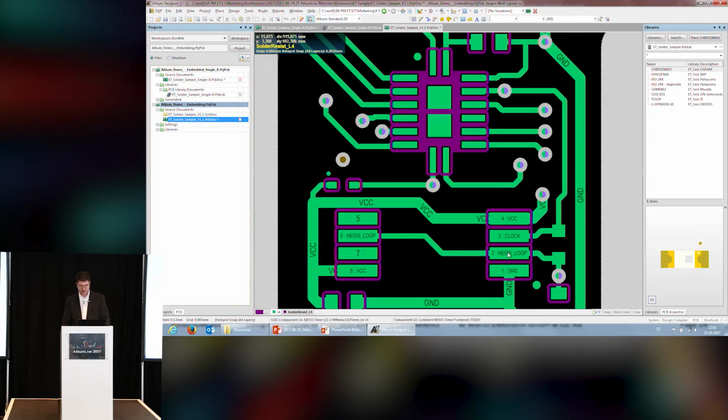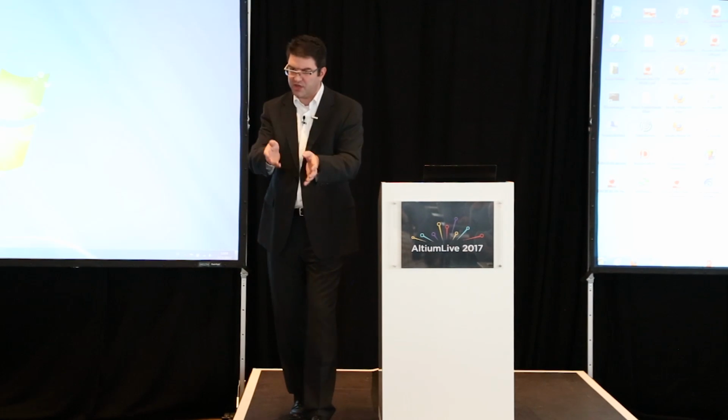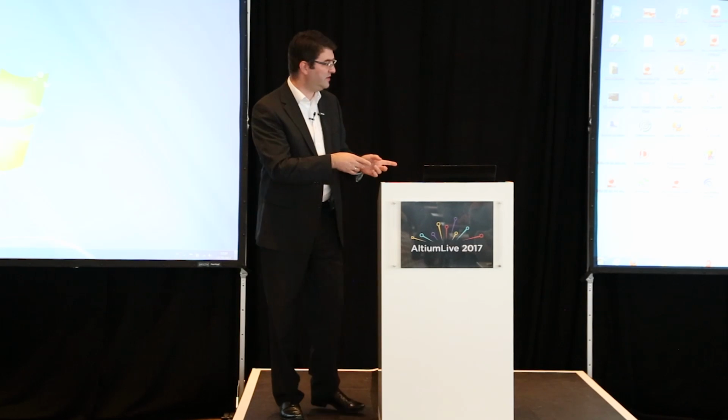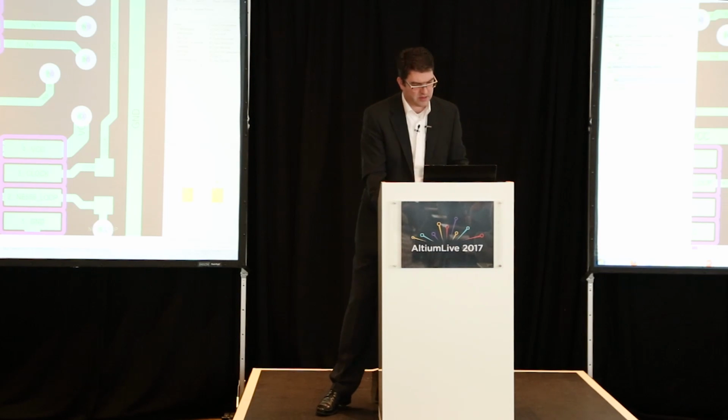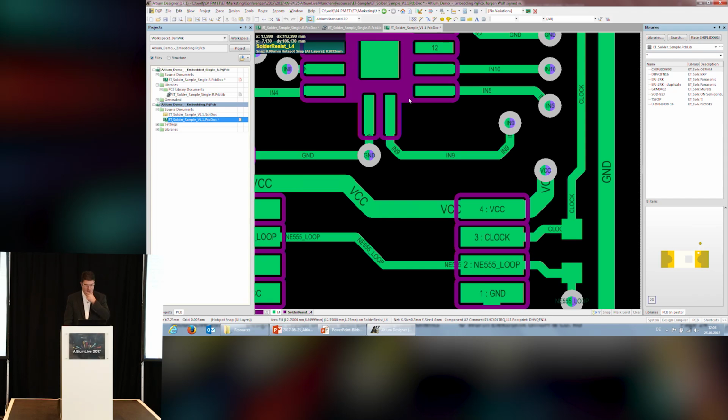So you can have those small frames. And the only difference from an outer layer of solder resist is negative versus positive. On the outer layer, when you draw solder resist, this is the area where you do not want to have solder resist. In this case, it's easier because you're drawing the frames, where you want to have solder resist. So that's one difference. How this is actually done, basically, you're just drawing a frame surrounding your pads and so on. So that's rather straightforward.